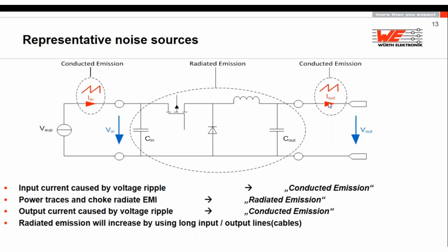But the most dangerous, look what is happening here. First of all, you have an input capacitor. With the input capacitor, you charge this energy in the input capacitance, then transfer it through the switch into this inductor and to this output capacitance. If you are a radio amateur, you know that two capacitors with an inductance in between, it means this is your dipole antenna.